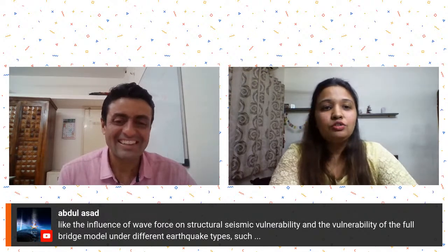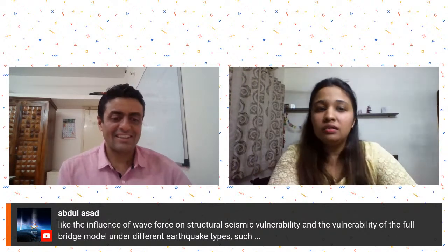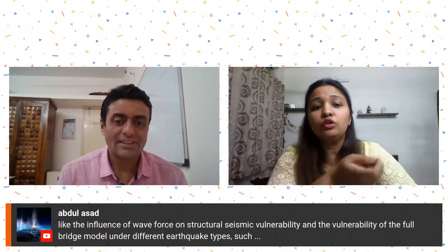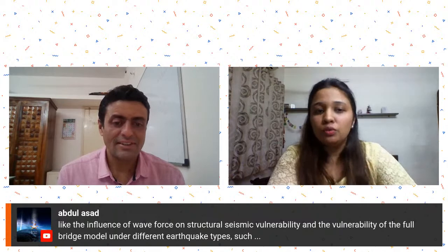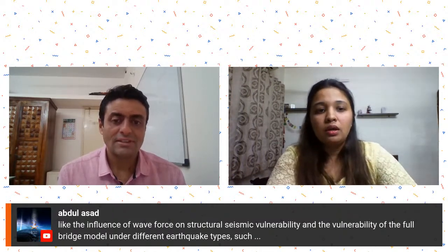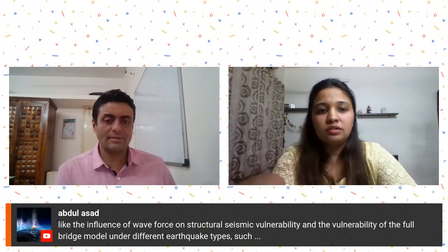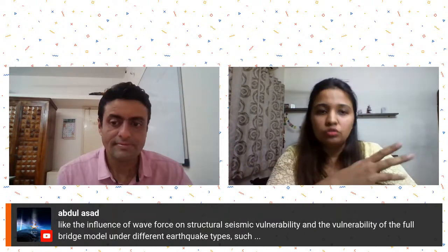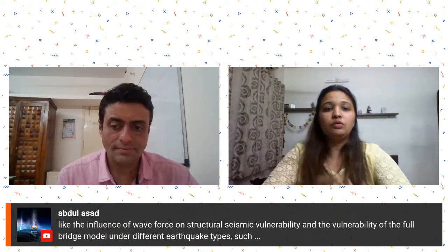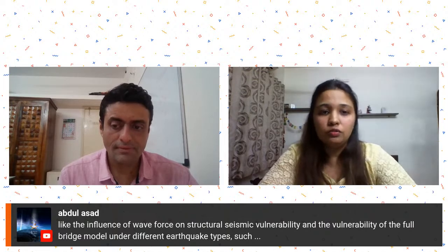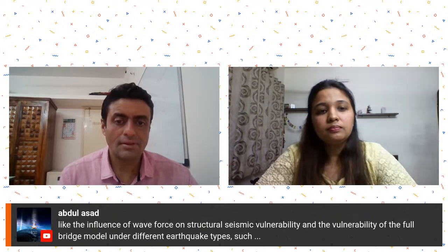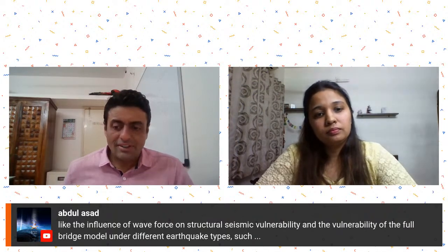So it is not different, but the loading pattern is different. I guess there is standing water in bridges. Then you have to consider the effect of tides, high tides and low tides. Some additional forces you have to take into consideration when you are constructing a bridge in the sea as compared to a normal river. And also the exposure condition is different. You have to take the marine environment into consideration while designing, and detailing of the structure is important when you're designing it on the sea. Correct. Very interesting.